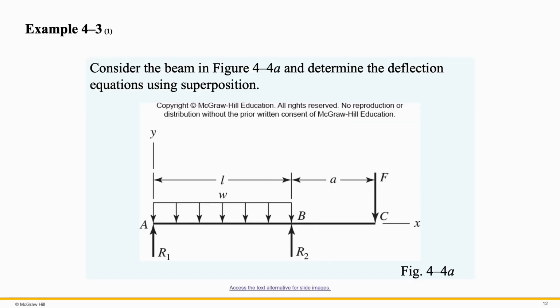In this example, we will apply the superposition method to determine the deflection equations. For this purpose, we will first analyze the impact of this transverse load F, and then analyze the impact of this distributed loading. We will analyze these impacts separately and then combine them in order to determine the total deflection of this beam.